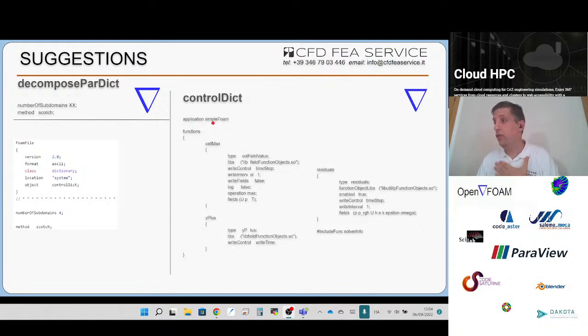And then another thing which I recommend as an OpenFOAM user is to add what we call the function objects. These are tools that tell OpenFOAM to generate, let's say, a CSV file with information of your running analysis, like the maximum of velocity, pressure, and temperature all over the domain, like the Y plus, or the residuals. These function objects are very useful because you automatically generate a CSV file, I simplified that a little bit, which can be opened in Excel and gives you access to this type of information.